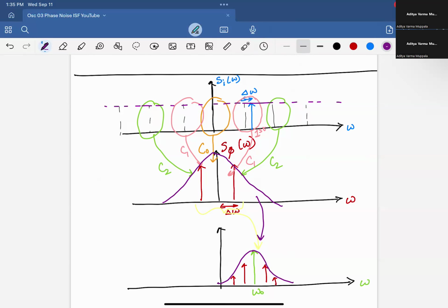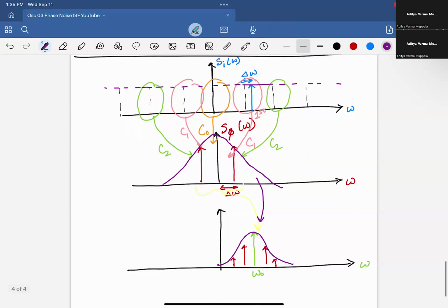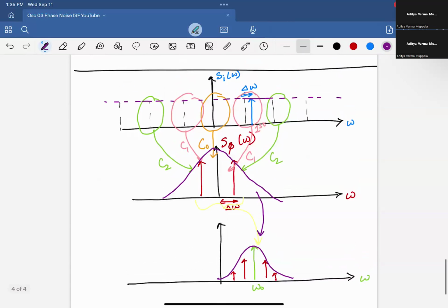It's not an exact copy, it's a phase modulation. So it depends on the modulation index, how that happens. But the modulation index is usually small because these noise signals are very weak compared to the main signal power, right? So because it's small, you can approximate it as just bringing it down almost exactly. Okay. So hopefully that makes this whole process clear.